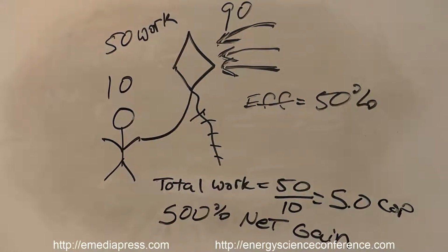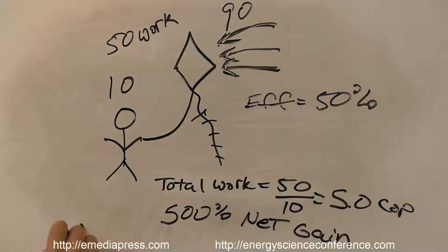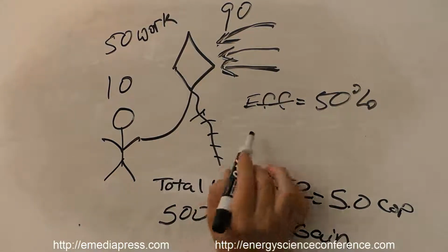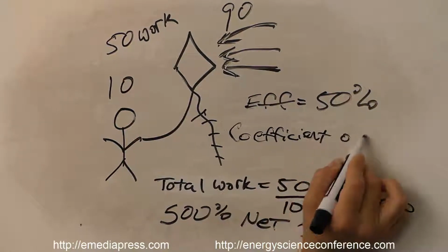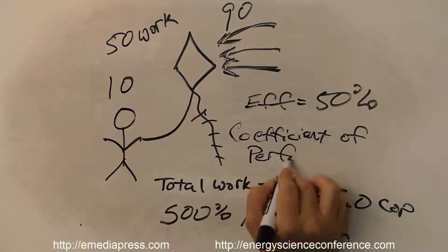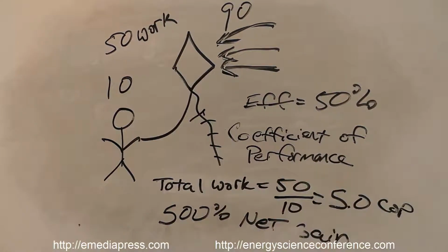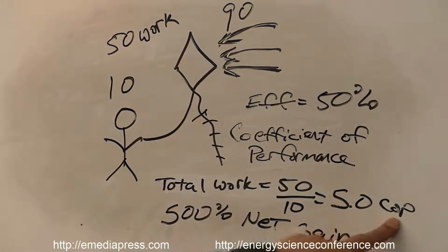And many of the geothermal heat pumps, some of them are getting up to 600-700% more than what you have to pay for electricity, because heat in the ground contributes free potential energy, and that energy is coming into the system, turning the water warm, and that gets pumped through your home, or it's pulling heat out of your home and depositing it into the ground during the hot season. But in any case, the COP stands for coefficient of performance. Okay, COP, and this is how heat pumps are rated.